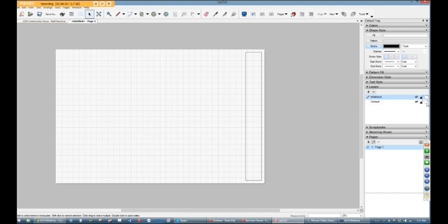And what does that mean? Every page you make, that information will show up on other pages. So title block's pretty good opportunity for that, right? You'd want that to show up on every page. So I'm going to set that layer to on every page, or shared, I guess is the right terminology.